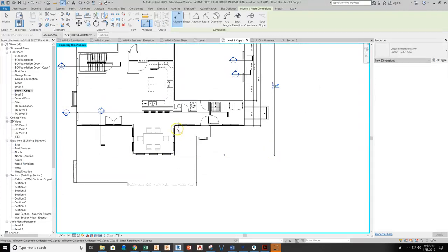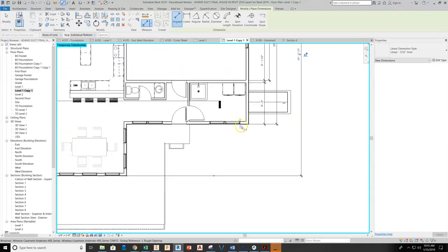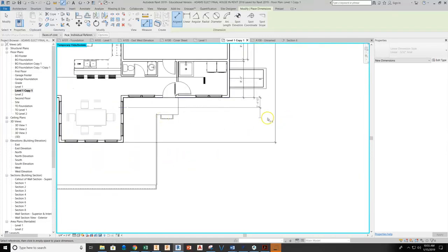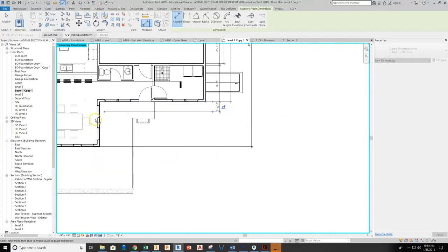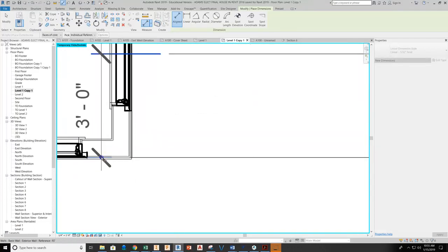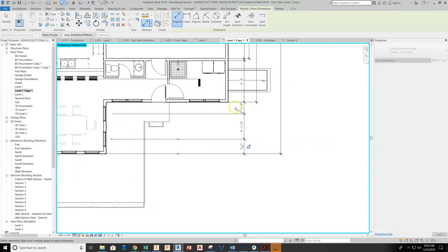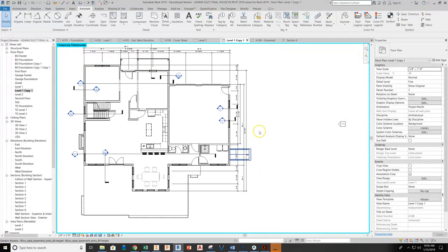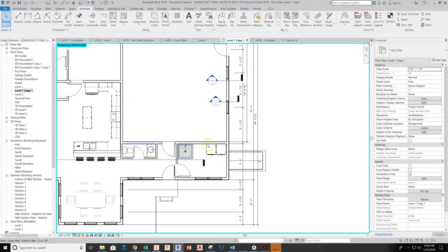And as I go, I can see that I need to do some dimensioning on these windows. So again, I'll go from sheeting face to center of window and pull those out to here as well. And then center of window, and you can see how this process just repeats itself all the way around the structure. So with that being set up, it seems fairly simple now to go ahead and cleanly dimension your drawing, and you just keep working your way around. So that's external wall dimensioning, where it can actually locate some internal walls.